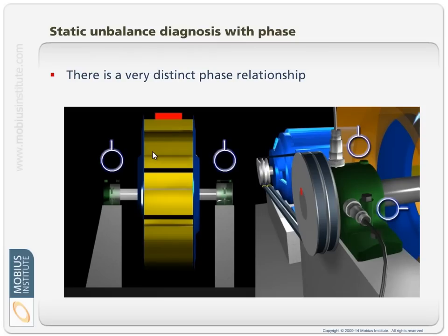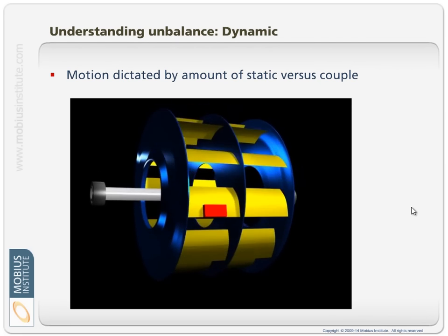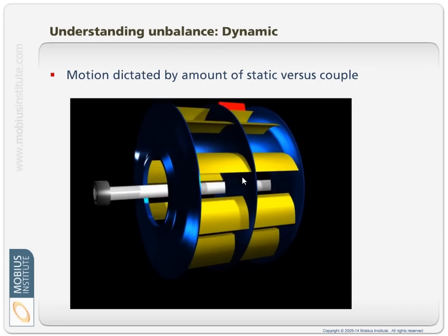How's it moving? So we come up with these little diagrams. We say, okay, the little circle and the line at the top is sort of like a reference. Rather than writing down the actual phase readings, we just draw it this way. So because the little line's going up in both cases, that means it's in phase. Because one's going at 12 o'clock and one's at 3 o'clock, that means there's a 90 degrees phase change, and it confirms unbalance.